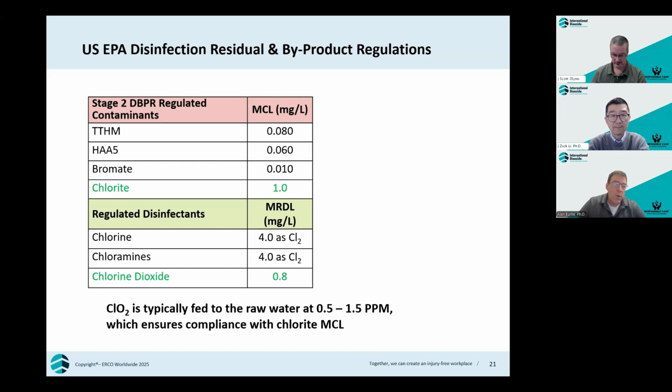At the time, ozone processes were monitored, and a main issue that arose was that bromate can be formed readily if bromide pre-exists in the source waters. So that is also monitored and plays a role here. There's not one disinfectant that's really a silver bullet to prevent all of these, but by using them in combination, you can achieve satisfactory results.